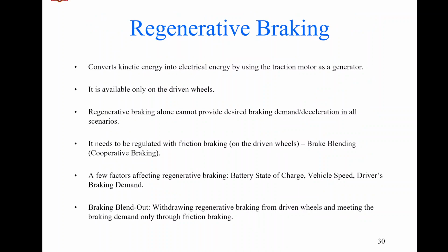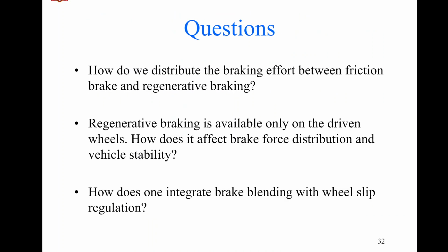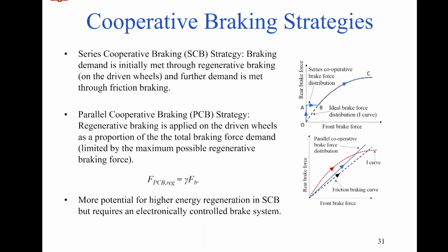So we were having a discussion on regenerative braking, and we took a look at regenerative braking in terms of what its objective is, what questions we should ask to meet our objective, and how various components in the electric vehicle would affect the regenerative braking. So, coming to the cooperative braking strategies, first is series cooperative braking strategy.